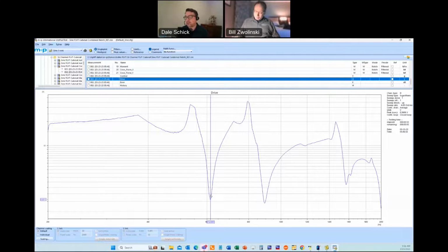I would look at the voltages put out by your drive signal to your shaker. I would do a pre-test analysis with the scaled limits for your cross-axis, and then try to determine whether or not those will be adequate to slow down the inertia of the system throughout that cross-axis response. But that's a great question. I think Nicolay asked that. Appreciate that.